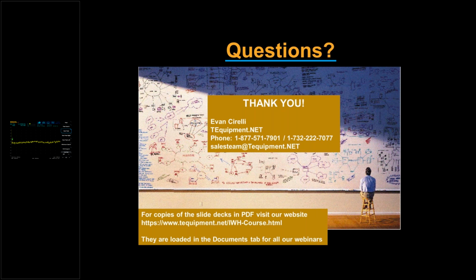So what we do is we look at the full span first, identify areas of interest, and then we can switch over to real time and get our seamless view of some impressive capability and depth on those signals. So I use the general purpose swept mode both for looking at passive devices with the tracking generator, but also as a first phase debug tool. It lets you make sure you're looking at the right band, you're not missing any big problems before you zoom in and look at a 40 megahertz span in real time.